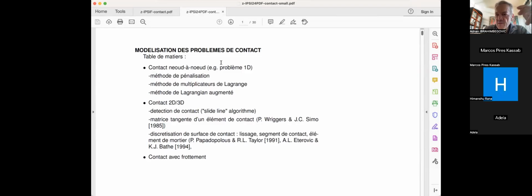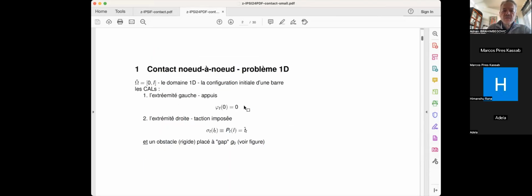The first approach was a simple contact element with one node of the slave body and two nodes on the master body. A paper by Rieger and Simo spelled out that one. Then they smoothed the surface with Hermite-type polynomials. And then you also had the mortar elements and things like this.